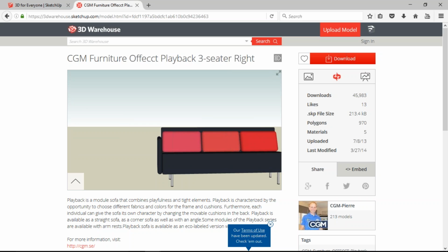Now, these details are pretty important to pay attention to when you're downloading 3D objects. Some SketchUp files can get very large in size, and not that Envisioneer can't handle the large files, but if you get too many large files into your Envisioneer model, you're going to experience some slowdown, some lag, some stress on your video card, just because the file size is getting so large because you've got so many objects and so much geometry in your model.